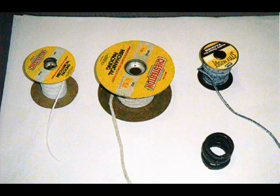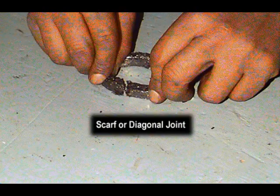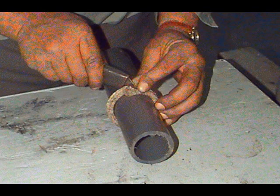Packing can be purchased by the roll or in individually cut rings. When using coil or spiral packing, always cut the packing into separate rings. Never wind a coil of packing into a stuffing box. Rings can be cut either with butt joints or with diagonal joints. The best way to cut packing rings is to cut them on a dowel the same diameter as the shaft in the stuffing box area.